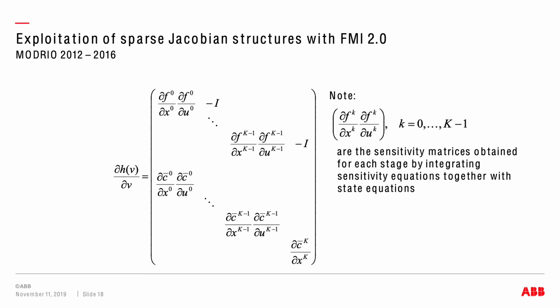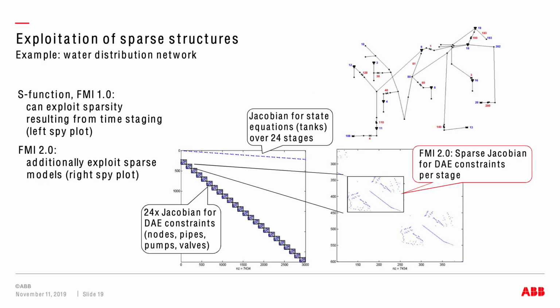And here we have the constraints which come from the outputs and limits on bus voltages, currents, and power flows that we have. Here's a screenshot. It's not from this application, but from a similar water network application. Here you see the Jacobian matrix, where we have the state equation here, and we have the constraint equations there in the Jacobian. And each of these blocks, of course, has a sparsity that we exploit during the optimization, as we have always been doing. But each of these blocks also has an intrinsic sparsity, which is determined by the network structure.